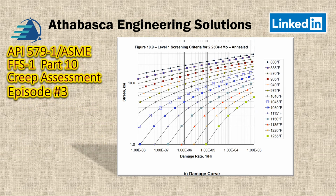And the first thing we're going to look at is what API calls the damage curves. We know from our evaluations earlier that this is considered to be a 2 1/4 chrome 1 moly annealed material. So we would go to table 10.9 and we pull this chart out. Now we calculated the maximum stress to be 4 KSI, and our temperature here is for our case 1, our long-term situation.